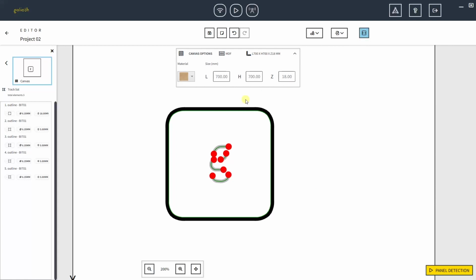Tabs are useful for through cut. Tabs work as links between the cut piece and the rest of the panel, allowing Goliath to move over the piece without moving the piece itself. They can be easily cut by hand at the end of the project. In this case, there is only one through cut, the outside square.